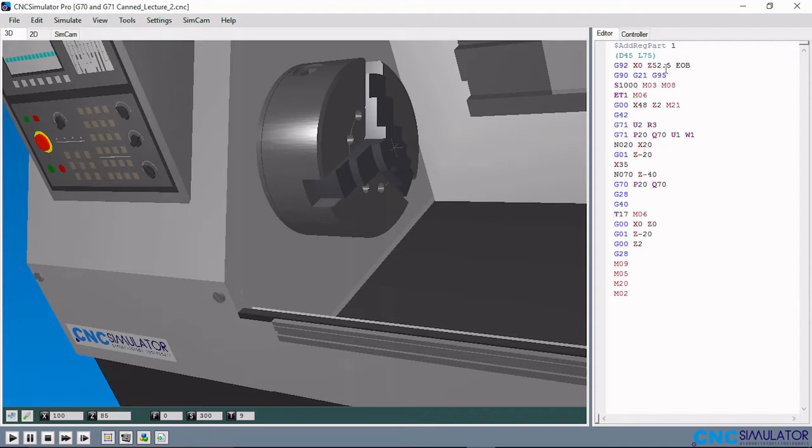And because the surface of the workpiece has been set to 0 with G92 here, moving into the workpiece towards the headstock will be a negative value for Z. So that means the length of the 20 mm diameter will be 20 on the workpiece. That is what this line of code is doing within the G71. So that means from 48 to 20 mm, it will be taking 2 mm at each cut and retracting 3 mm to get to 20 mm from 48 mm. That will be the procedure.